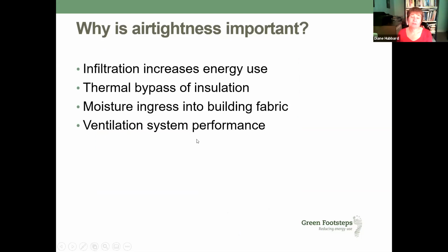So why is air tightness important? Well, if we've got all this unwanted air moving around in the building, then we're basically increasing energy use. Now, the thing about air is it actually takes relatively little energy to heat air compared to other materials like water or concrete or brick. But it does increase the energy use. With this infiltration, the air change rate in your home increases. So what you find in some buildings is they're particularly difficult to heat in cooler weather, and in windier weather, because the wind forces the air to change through the property more frequently. So your heating system physically can't keep up. So infiltration increases energy use.